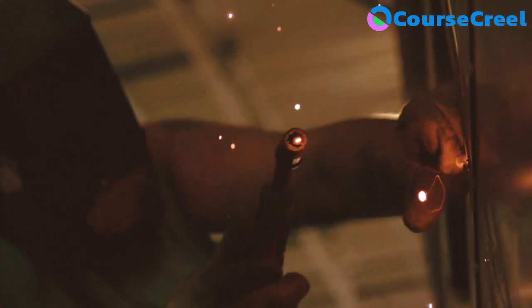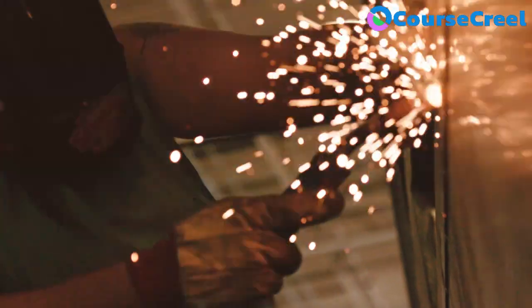But we need to follow some more precautions in terms of the welding materials, or the material which has to be joined. The surfaces which are joined together are called interface surfaces. The interface surfaces should be clean because impurities like oil, dirt, etc. would interfere with the metal during welding, which can weaken the joint. So this is one precaution we need to follow when we are joining two materials.